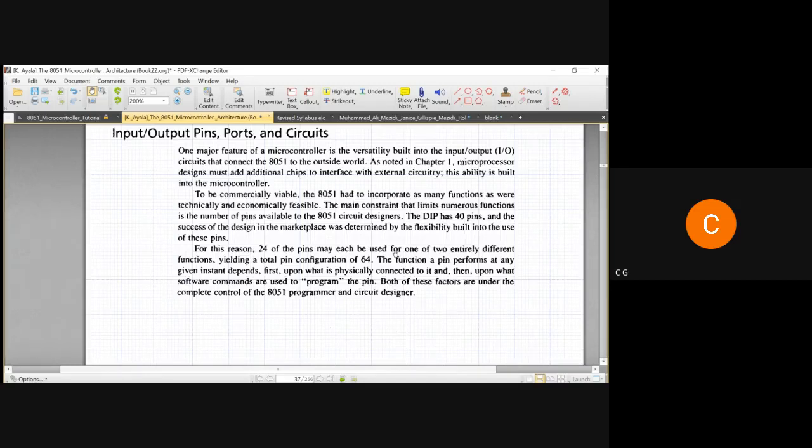Then we have seen in the video that the operating frequency is some 20 megahertz maximum, and that too only for the 8051 C or D, the high-end 8051 microcontroller. So around 8 megahertz to 20 megahertz it can operate. The working frequency can be manipulated externally; whatever quartz oscillator you employ will decide the working frequency. But maximum 20 megahertz it will work, so 20 into 10 raised to 6 operations we can say that it can perform.